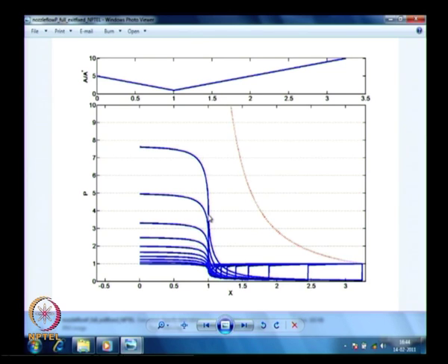If I do this particular experiment of keeping my back pressure fixed, not exit pressure, back pressure fixed, and I increase my P naught on this side, then it will decrease my P star for a little bit and then it will keep on increasing my P star because my P naught is increasing.